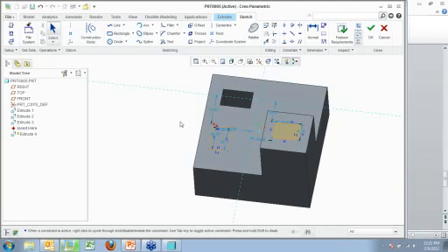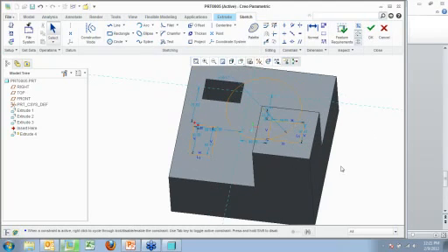Suddenly, now your revolve feature doesn't complete anymore. Well, now you can see that's what happened. It'll actually highlight that for you. Then also, if I've got a circle that overlaps this, now it's not shading as a closed loop, but if I turn this on, it'll actually highlight. I can select this and it'll highlight which parts overlap in red there. So it's little things again like that help speed things up.